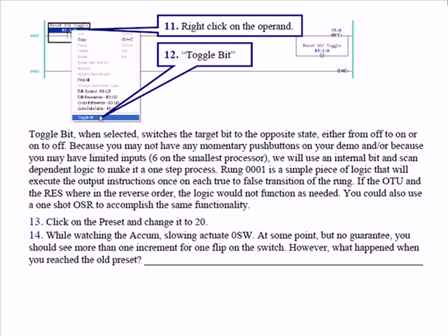We dropped the filter down to 0.07 to increase the possibility of the high-speed counter picking up switch bounce. In other words, when the contacts go closed, they actually bounce. They make contact, open up again, and then close again. So with the filter set to as high a response as possible, you're more likely to get switch bounce. You may or may not.